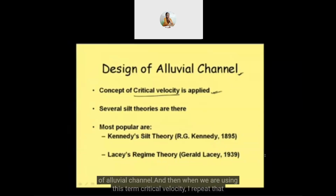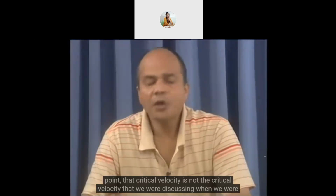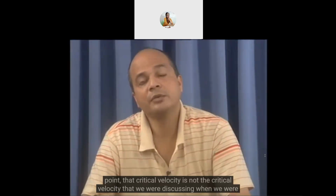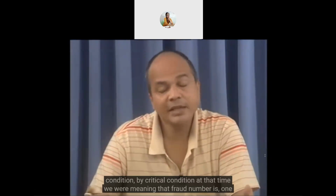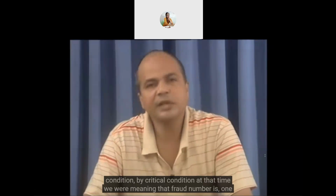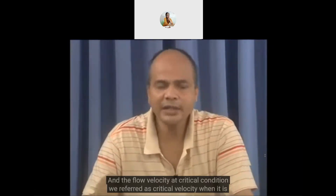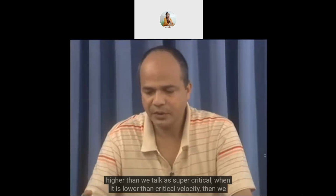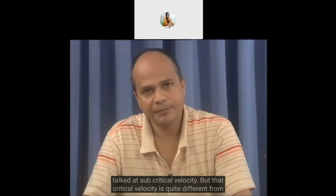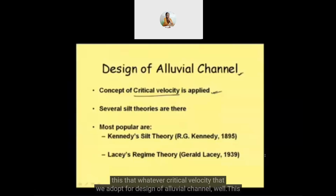And when we are using this term critical velocity, I repeat that point, that this critical velocity is not the critical velocity that we were discussing when we were discussing critical flow. When the flow is in critical condition, we meant that Froude number is 1 and energy is minimum. So those conditions were there for critical depth. And the flow velocity at critical condition we referred to as critical velocity. When it is higher, we called it supercritical. When it is lower than critical velocity, we called it subcritical. But that critical velocity is quite different from this critical velocity that we adopt for design of alluvial channel.